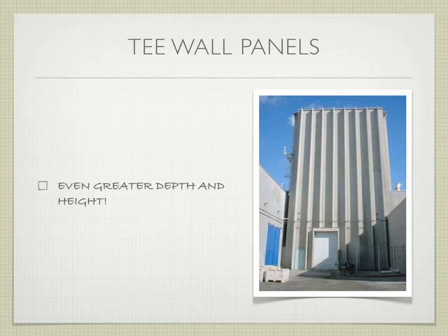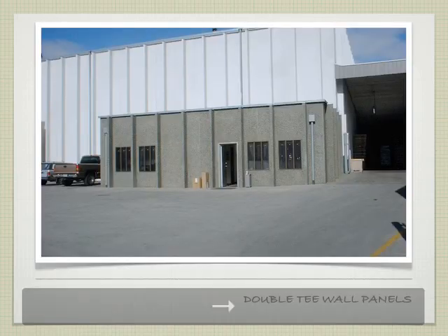Windows, right? So if we're thinking about these precast elements as wall panels, they're really efficient if we have a building that doesn't need windows and doesn't need openings, and we could just shell it in. In this particular example, this door is relatively easy because it's in between two panels. This took a lot of effort to figure out how to make that door fit. Up above here, no windows, no openings, really efficient, really economical. But if we wanted that to be full of windows, this system wouldn't be that economical, nor would it be as structurally sound.